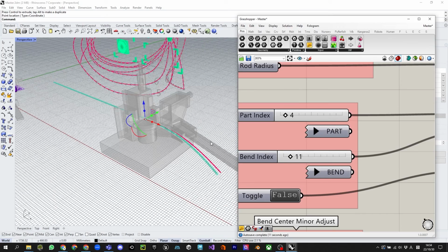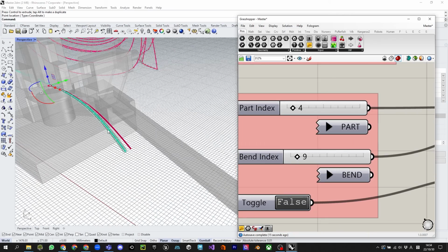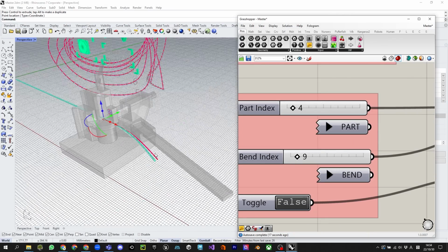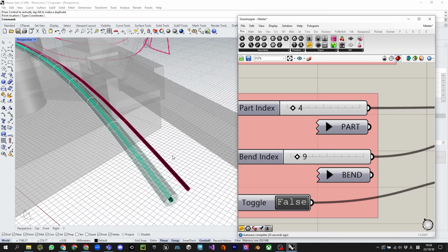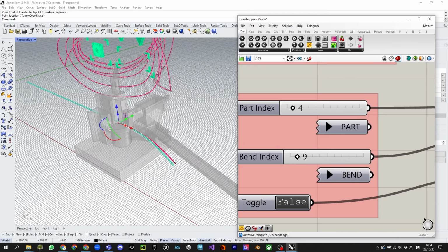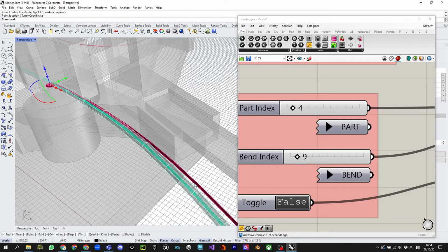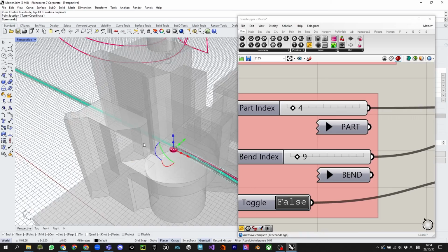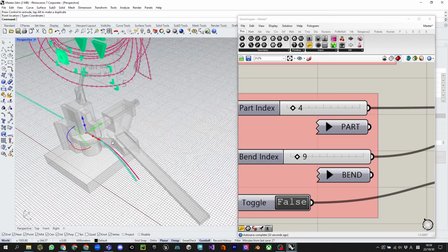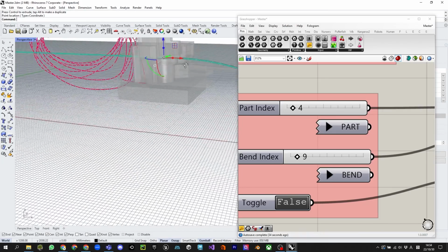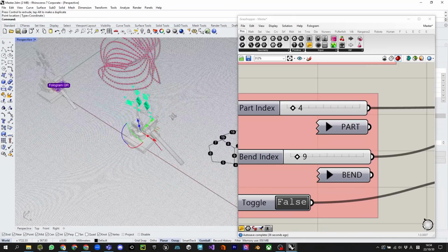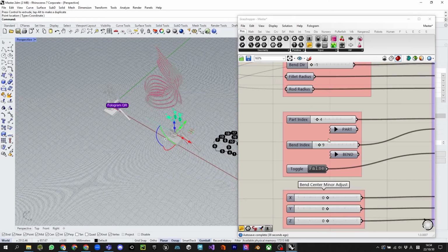So you see that when you are here, you see 2 curves, right? What this means is this pink thing is the position that you want to position your material at before the bend, and then you want to match to this green position after you bend. So you're just bending that much, but that is a good guide to help you position your bend.